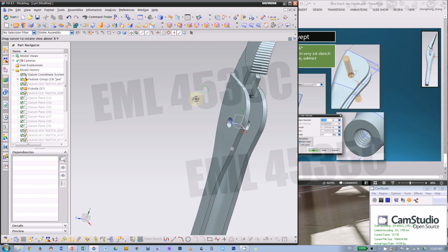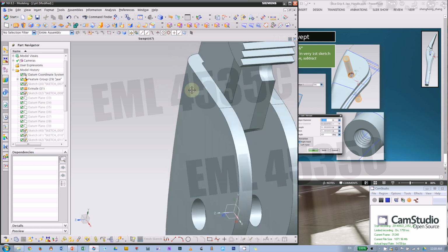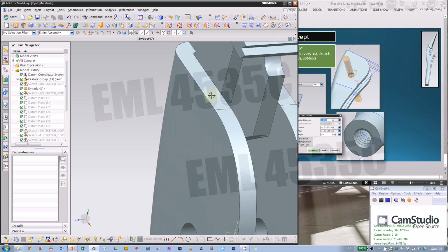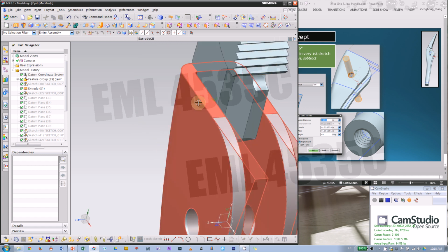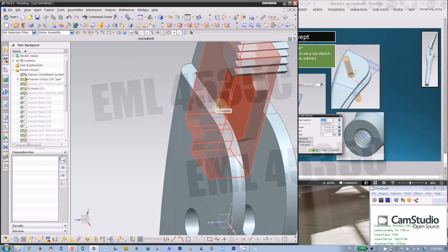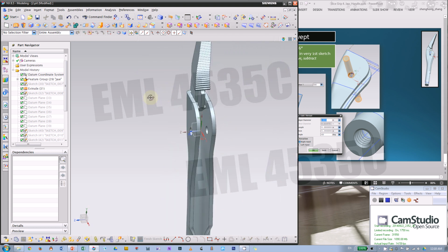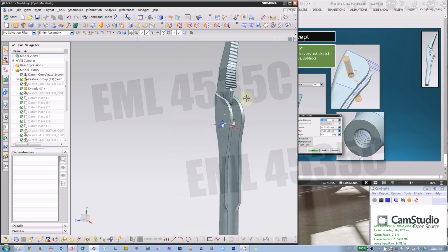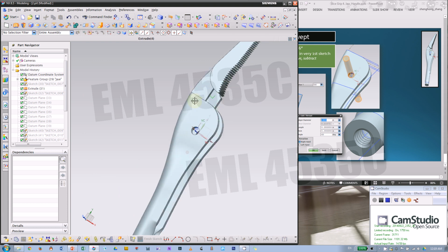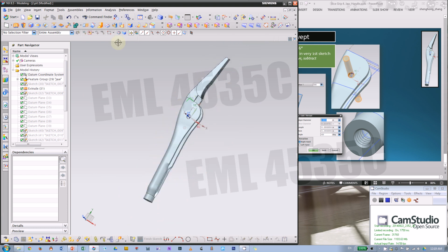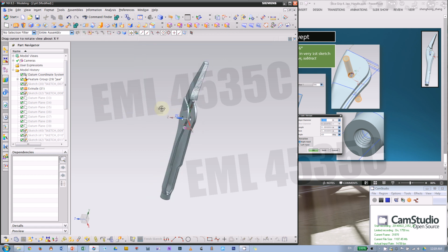So it doesn't matter that much because in the fan we'll use the outside face for the fan. That's a 2D shell. Then in between the jaw portion and the shell, we're gonna use glue. So it doesn't matter what geometry you have in the middle. So I'm just being lazy and skip this part. Okay, if you like to, you can find some kind of a sketch here and fill this in. And if you like to, also you can unite those two pieces into one solid body.